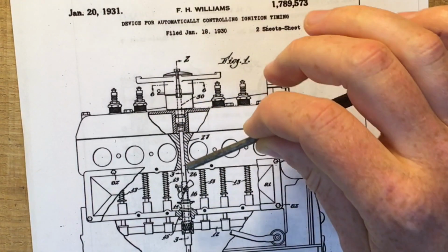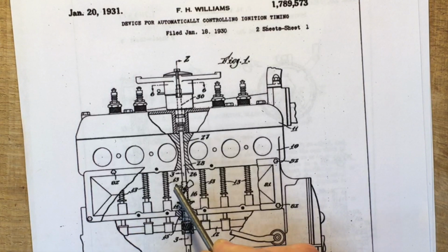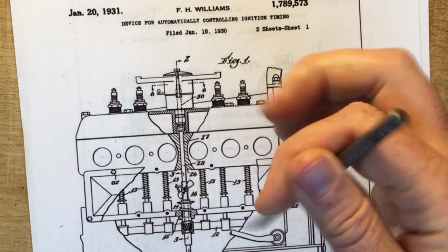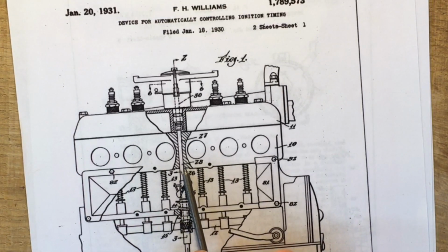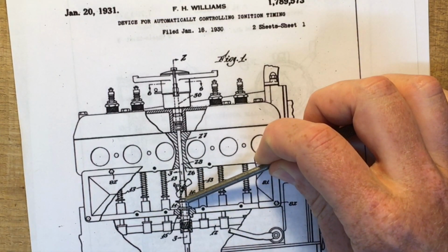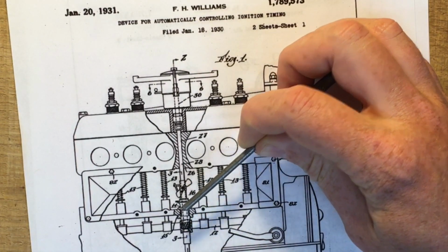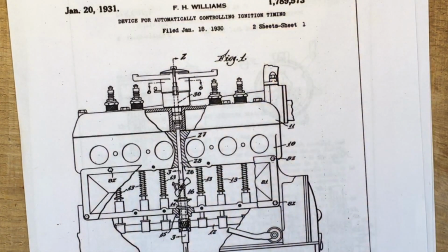Now, in the stock engine, around this shaft, there is the drive gear coil spring, and that spring pushes against the top of the valve chamber and holds this bearing assembly down against the bottom of the valve chamber. But the Williams device is supposed to replace part of the lower shaft, and once you do that, the drive gear spring won't fit around it.